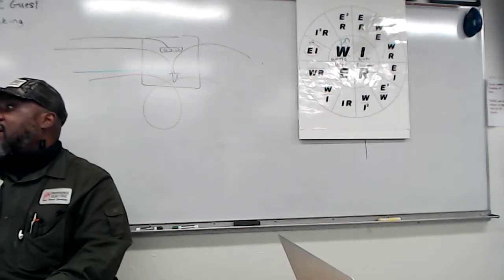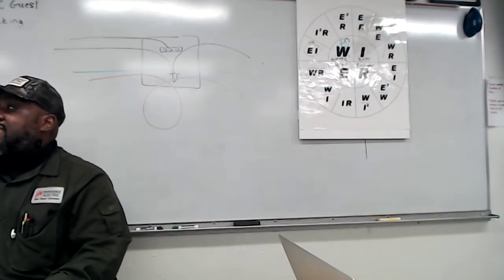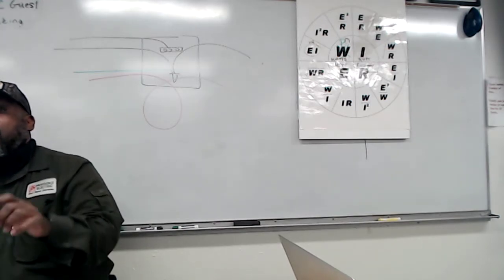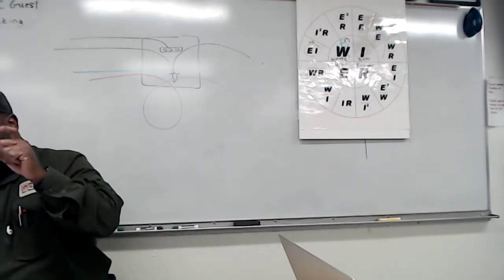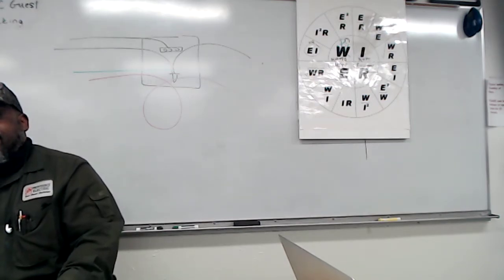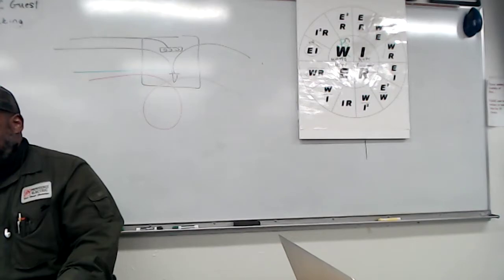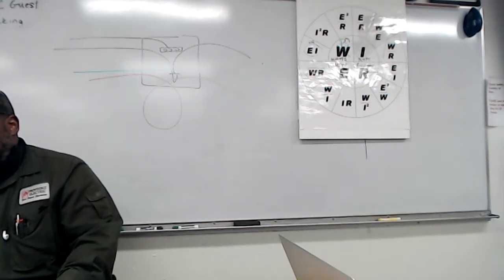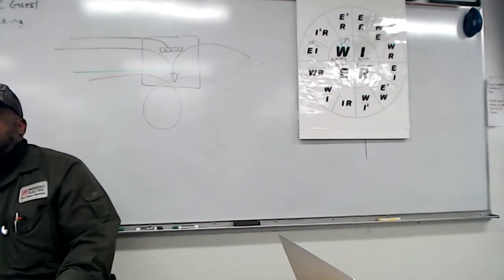If you look at this plug over here on the wall, it's actually mounted on a yoke. That piece that you use to screw that plug in, that's called the yoke. What if it just has the plug in? Like with the double plugs with the double USBs in the center of it, they just plug in. It's still on a yoke. You can't put a device in a box without a yoke.